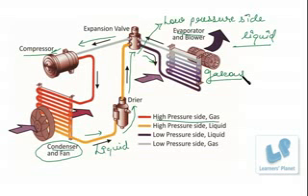We'll also discuss it in more detail, right? So basically here the working fluid leaves the compressor as a hot high pressure gas and flows into the condenser. If we look at the air conditioner part outside a room or a house, we have to look at the part that has metal fins all around. The fins act just like a radiator in a car, and help the heat dissipate more quickly. Now what happens when the working fluid leaves the condenser? Its temperature is much cooler and it has changed from a gas to a liquid under high pressure. Now what happens when the liquid goes into the evaporator through a very tiny narrow hole?